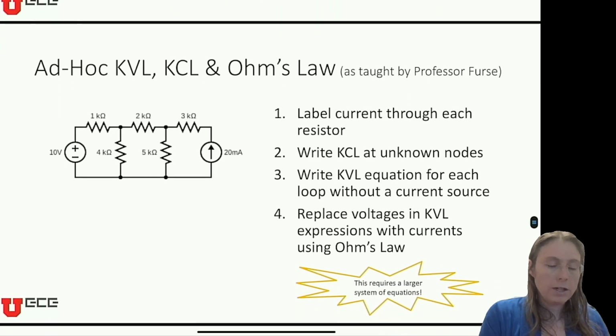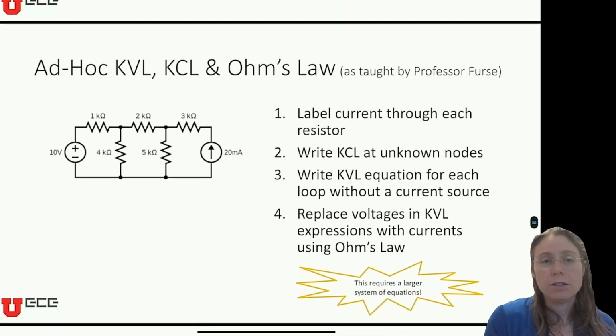The other method I want you to be aware of is kind of an ad hoc combination of KVL, KCL, and Ohm's law. This is how Professor First teaches it in the intro course. I would say it's easier to implement in the sense that you're only using KCL, KVL, and Ohm's law over and over and over again, which is what you learned in Unit 1. But the downside is that it requires a larger system of equations. So let's work through how you would do this ad hoc method for the circuit here on the screen.